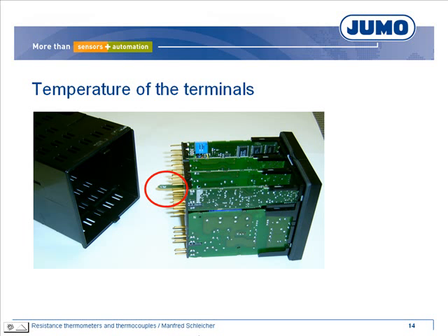Temperature 2 is the temperature of the terminals of the field device. This temperature is measured by an additional temperature sensor. The example shows a JUMO compact controller. The temperature of the terminals, temperature 2, is added on the calculated temperature differential. This is called internal temperature compensation.